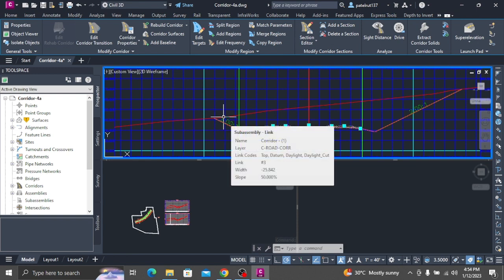View the corridor section at station 7+75.00 to view the grade at subsequent stations. Click Go to Next Station. Notice that the change you made is visible through station 11+00.00. At station 11+25.00, the centerline pivot value returns to pivot about centerline.